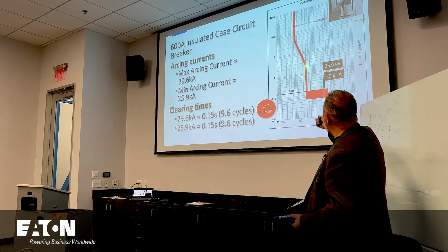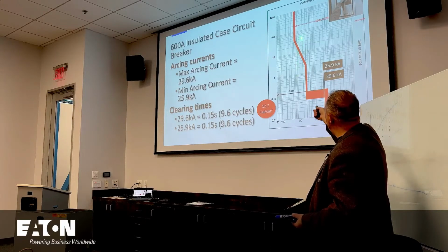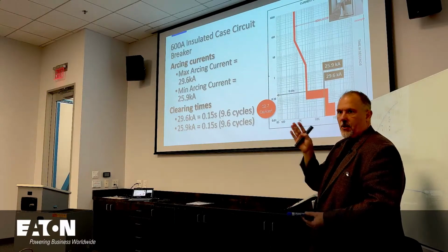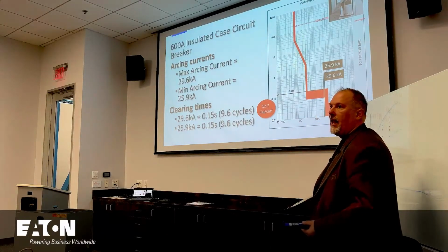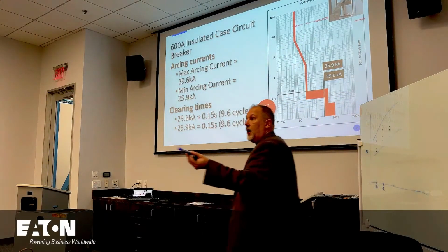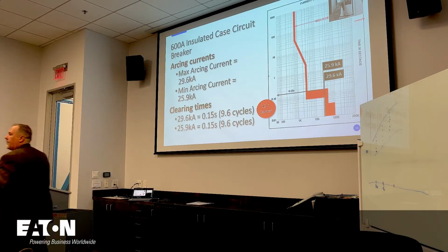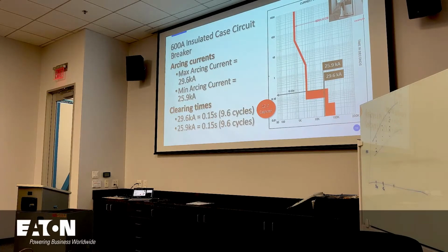Why would we adjust long time delay? That's a long time delay. Anytime I say delay, it's time. Pickup is current. Why would I adjust the long time delay? Motor startup, transformer inrush, motor startups or selective coordination, right?